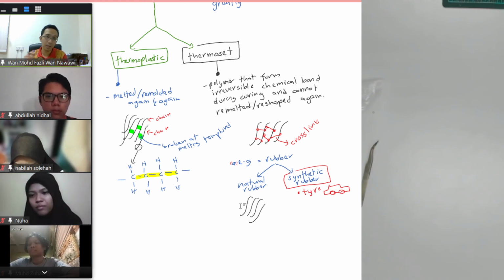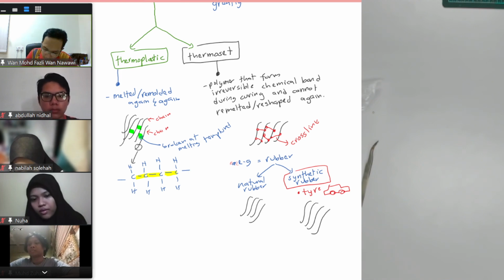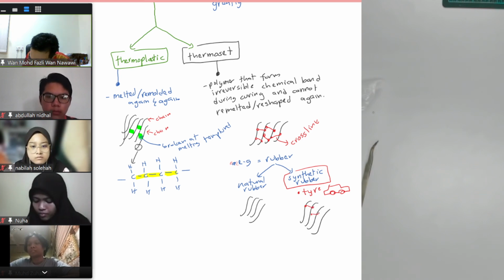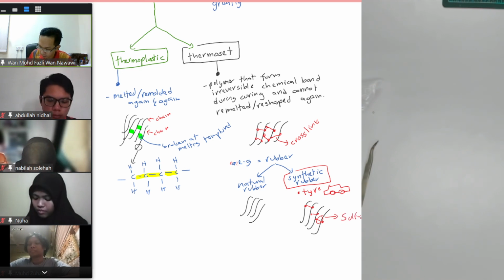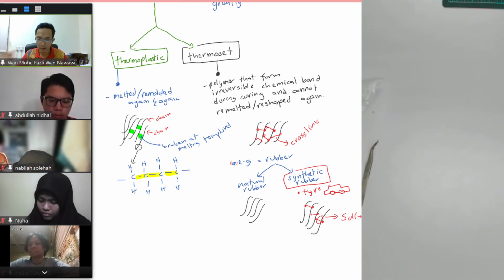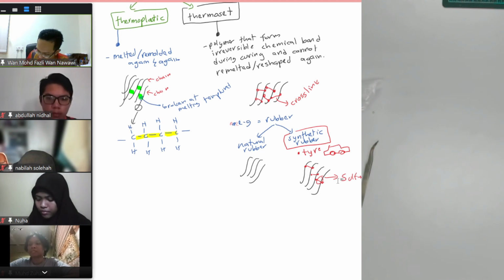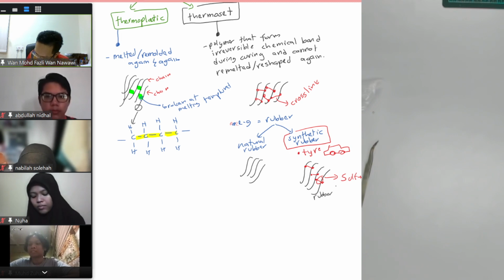So they do something to that rubber. What they do is that you have still the same chain, but between this chain they put sulfur. Between this chain they put the sulfur, meaning they have this rubber and then they mix it with the sulfur. They mix in the sulfur at high temperature. So basically you take rubber here, and you mix the rubber chain with the sulfur here.